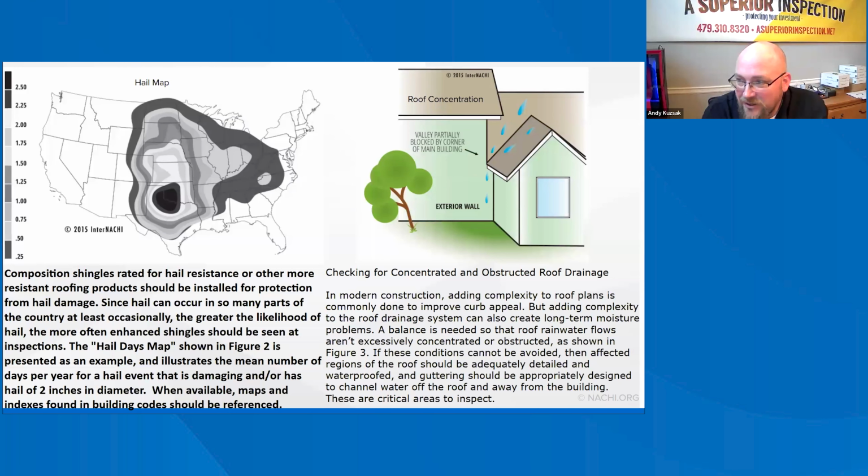Another consideration for protecting roofs from hail damage involves re-roofing. Re-roofing over an existing layer of composition shingles, while generally permitted by code, reduces the ability of newer shingles to resist impact damage from hail. Therefore, in hail-prone regions, the insurance industry recommends, and local code may require, that re-roofing should include removal of the existing layers of old composition shingle roofing.